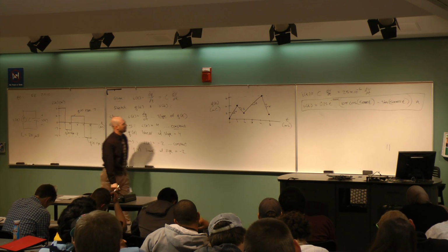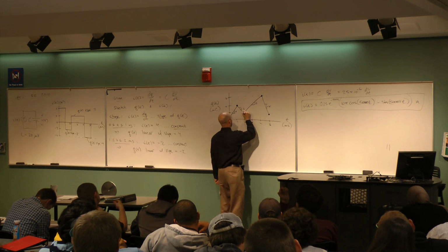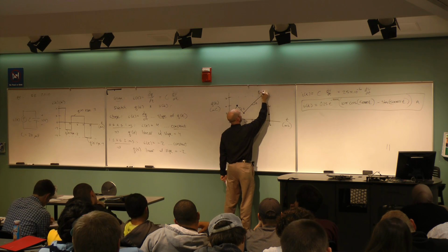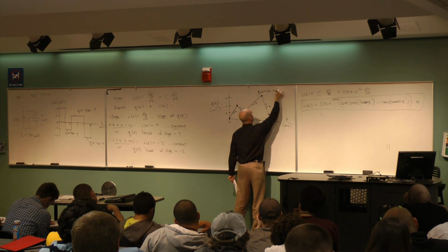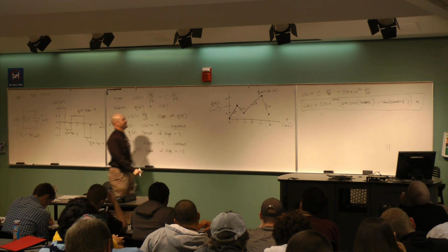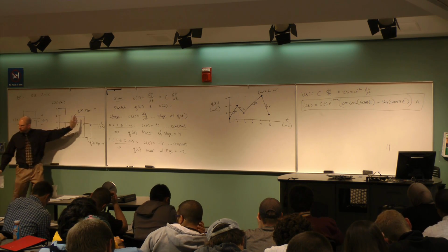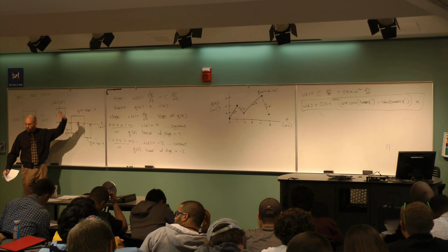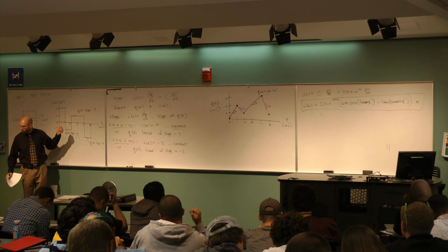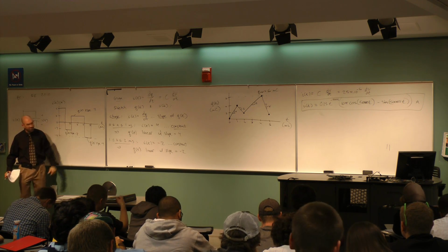So what's the maximum charge? Yeah, Q max is 6. Units are millicoulombs. So the point is, in each one of these intervals, I is constant, therefore Q is linear. The slope of that line is the value of the current. Questions on that?